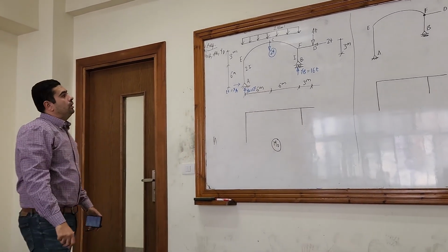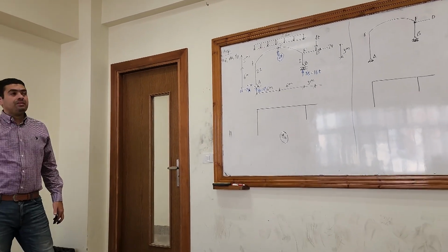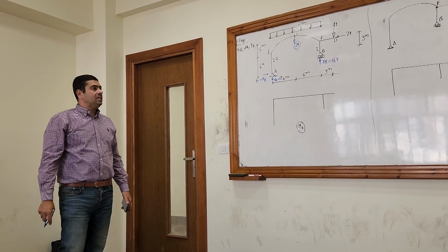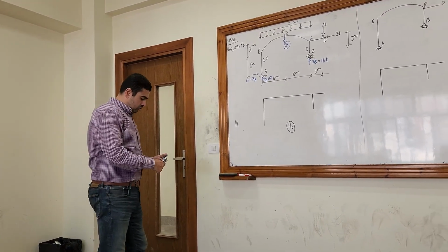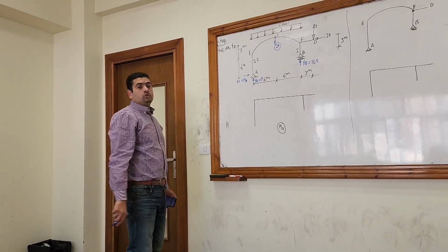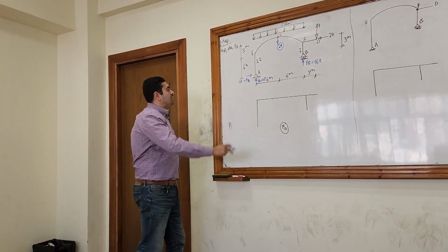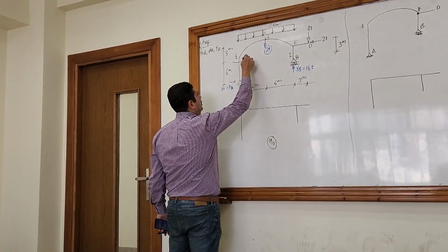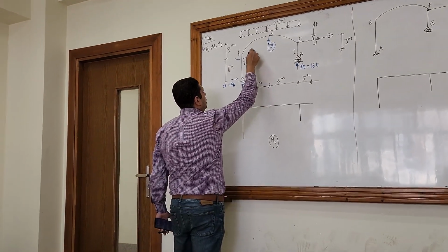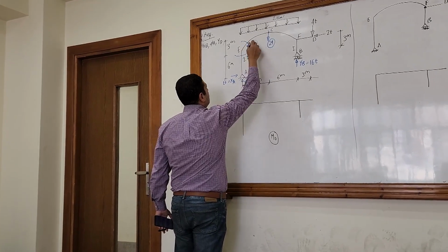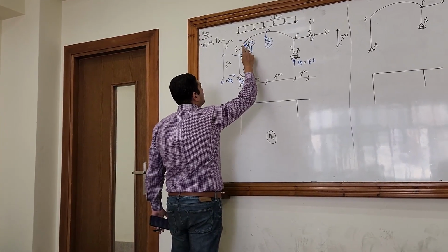Okay. Let's calculate the moment at the joints. How many joints do I have now? I have 2 joints, joint at E and joint at F. What about the moment at the joint at E? I think from EA is easier. So it's 2 times 6, 12. So the other side has to be equal to 12 as well, right?